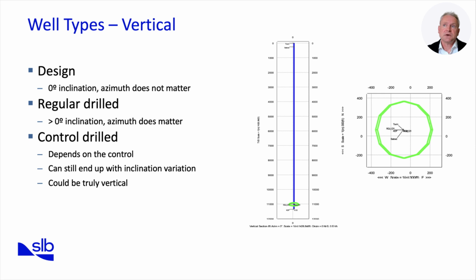With the introduction of rotary steerable systems, it is now possible to drill truly vertical wells. RSS tools counteract natural BHA tendencies and maintain precise trajectory control. This reduces spiraling, lowers torque and drag, and simplifies casing runs. Vertical wells remain a fundamental part of directional drilling. By understanding their limitations and using modern technologies, engineers can achieve straighter wells with fewer operational risks.